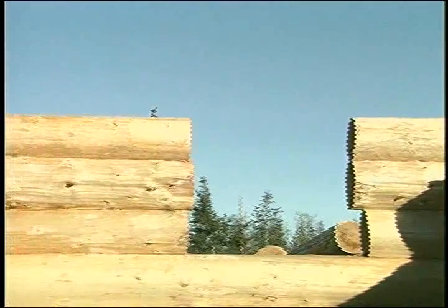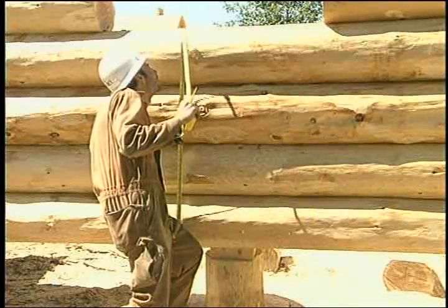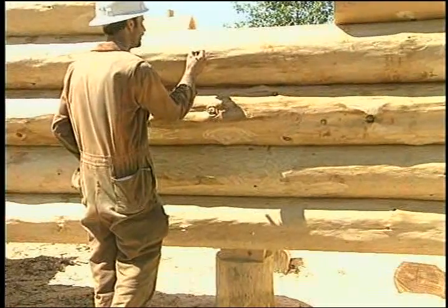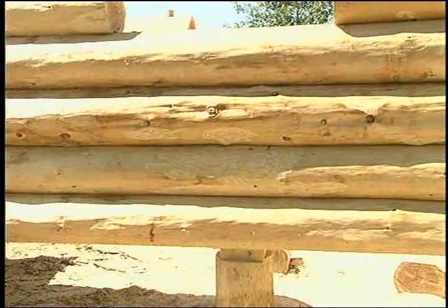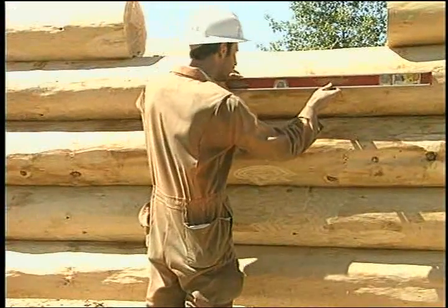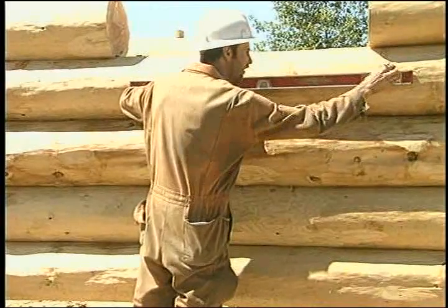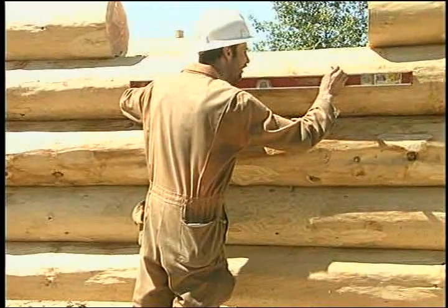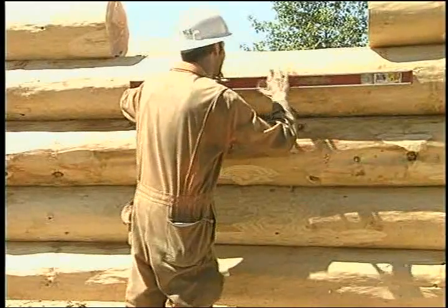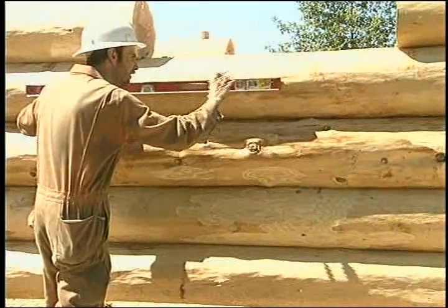The bottom of the opening need not be cut yet, but plan to locate this height a little above the midpoint of the log. In most cases, you will have the option of adjusting the window height to meet this criteria. If not, try to choose log sizes in advance to accomplish the purpose. Logs that are cut almost through make a poor lower sill position.